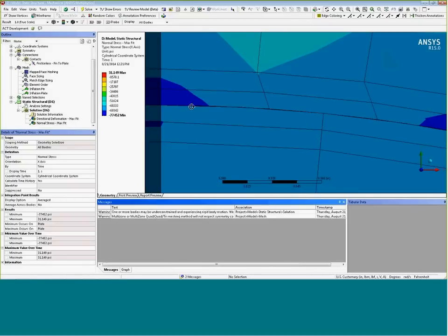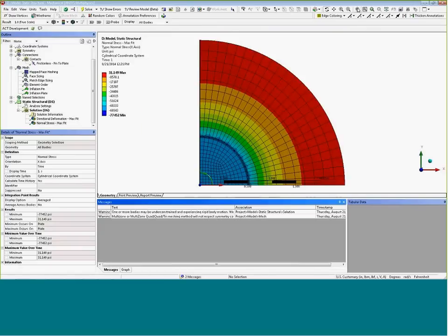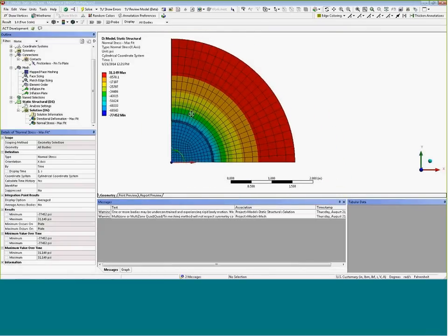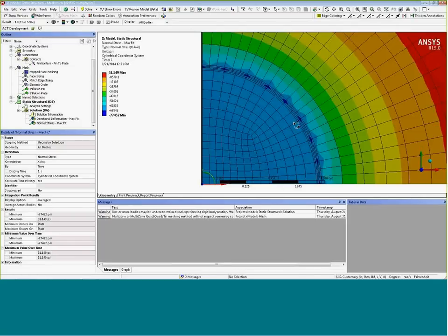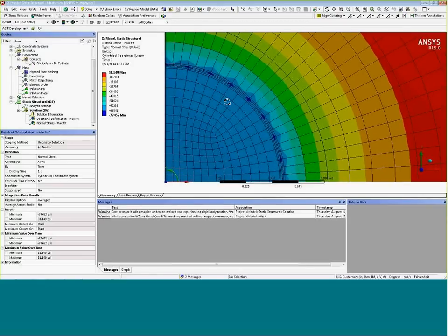So then it will represent that curved surface a little bit better through here. It's not straight anymore. And looking at these results, they're still not great. We're looking for 66 KSI at 77. The results are still somewhat irregular as you go around the circumference there, although it is better. And you could probably refine the mesh a whole bunch more, and then even though they're not lined up node to node, you could still probably get a pretty good answer.